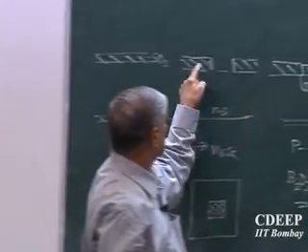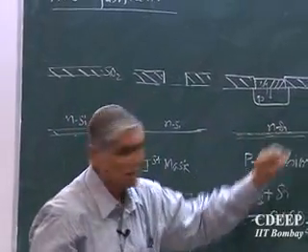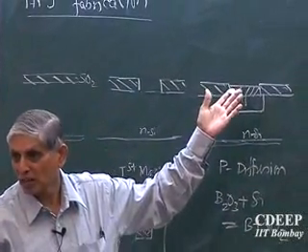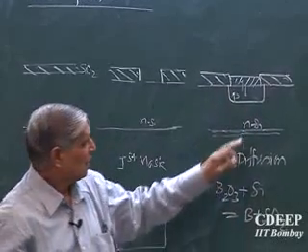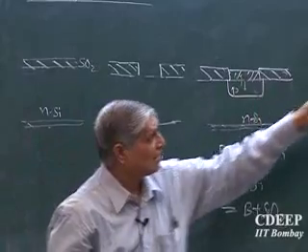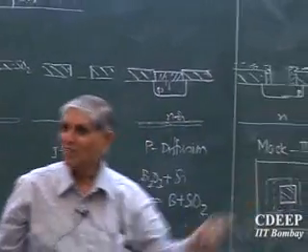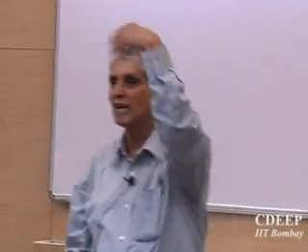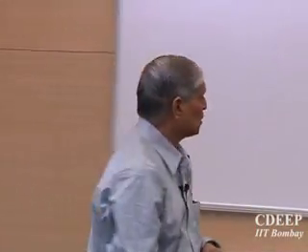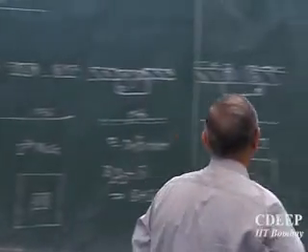However, during this process I will also have another oxidation, because I am doing SiO2. This process oxidation is going on. But when I etch this oxide, it will go. On the bottom we normally don't show anything, but the process happening above takes care of the bottom place. So now I need metallization.